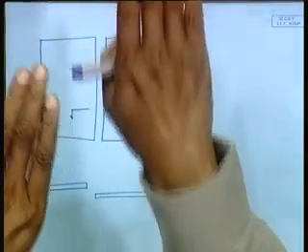The edge is not perfect. So, somewhere it is coming below it, somewhere it is going up. So, what will you do? You will have to align them by force, and the moment you do that by force, additional stresses are built up there. Additional stresses are built up. That will add to the thermal stresses and lead to more distortion.